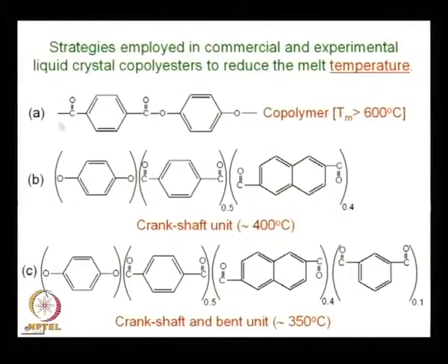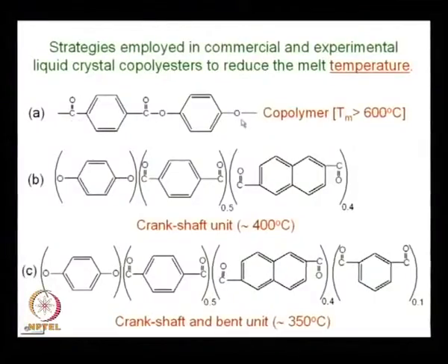So, you see here you can get again the correlations between molecular structure and its property. This melting point is a property. How the melting point is related to its structure, you can understand this thing, and which is again related to molecular order. That means, it will give you more packing, as well as the backbone chain contains rigid phenyl ring. You have seen in case of polystyrene that rigid phenyl ring remains as a pendant group.